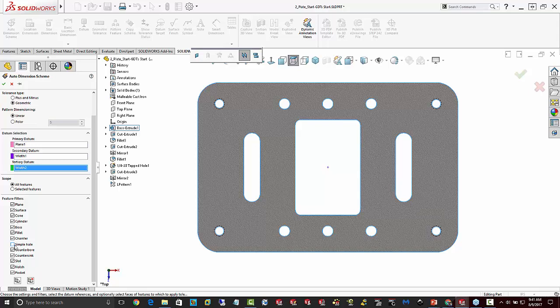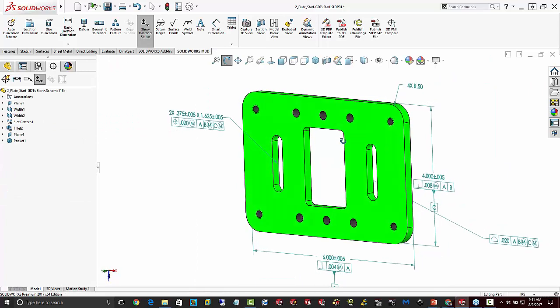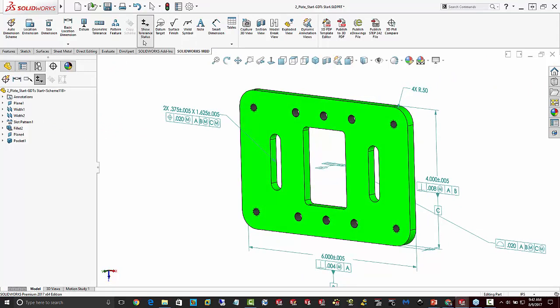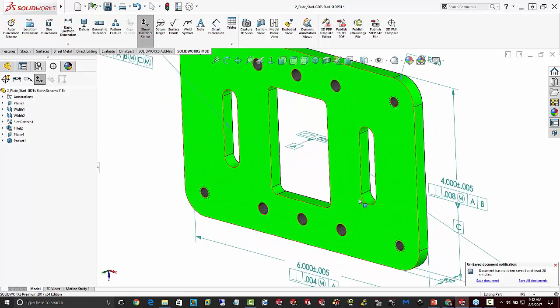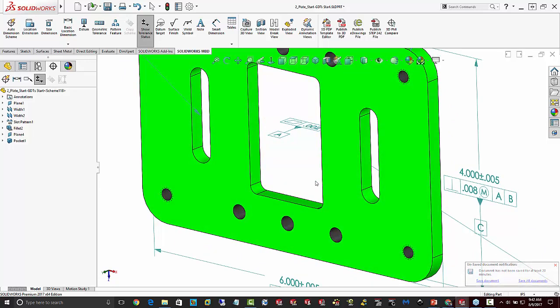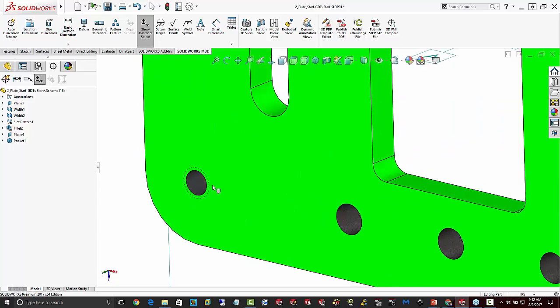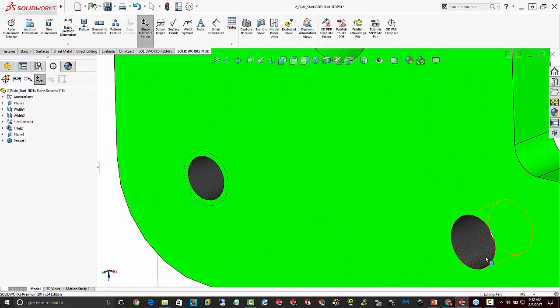Everything will get automatically defined for ASME Y14.41 and accept those holes, and then I'll come back in a secondary step and define those holes. So green, the tolerance status, green means that everything is fully defined. And it did everything that I wanted. All the radii, the profiles, the pockets, and the slots are all fully defined in a couple of clicks. And what's left is there's no definition on the tapped holes in these holes here.